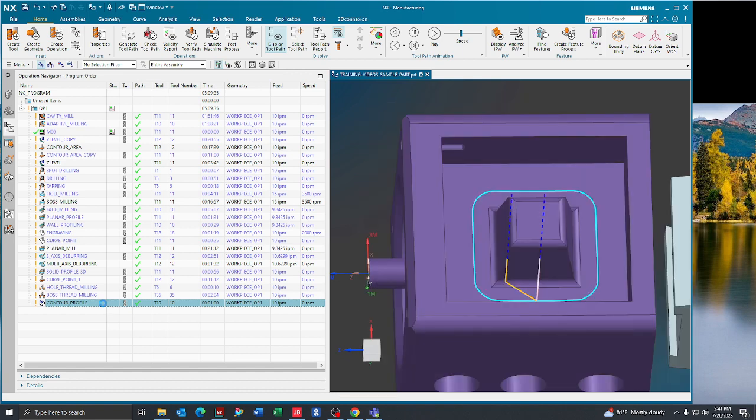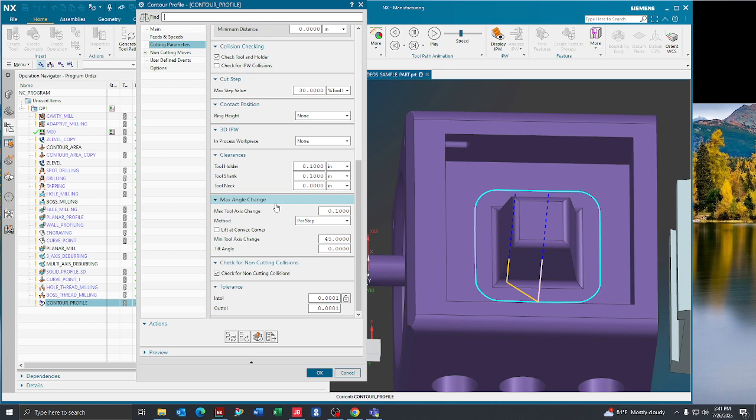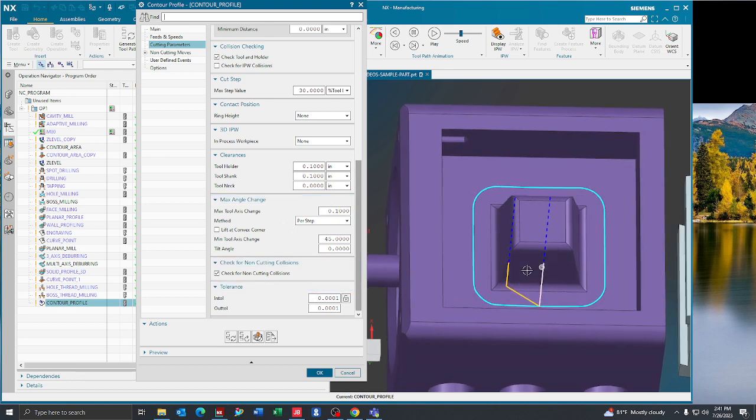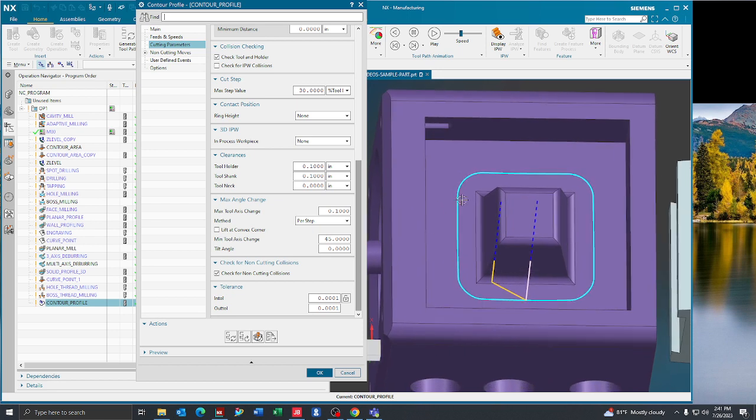When it does that, it's defining and looking at that model in those 100 thousandths of an inch steps or increments, and then it makes the motion a little bit more clean. But, so you know, as a reference, by doing this and dropping this down, it will make it look at it finer, but it will also add significantly more lines to the toolpath when post-processing, since it broke the toolpath up into 100 thou increments instead of large increments like it was set to before.